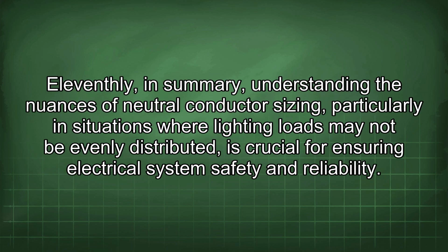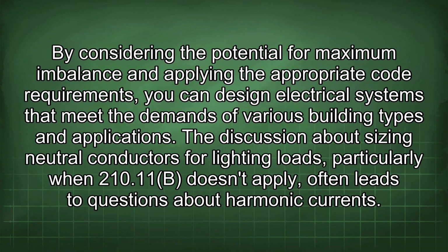11thly, in summary, understanding the nuances of neutral conductor sizing, particularly in situations where lighting loads may not be evenly distributed, is crucial for ensuring electrical system safety and reliability. By considering the potential for maximum imbalance and applying the appropriate code requirements, you can design electrical systems that meet the demands of various building types and applications.